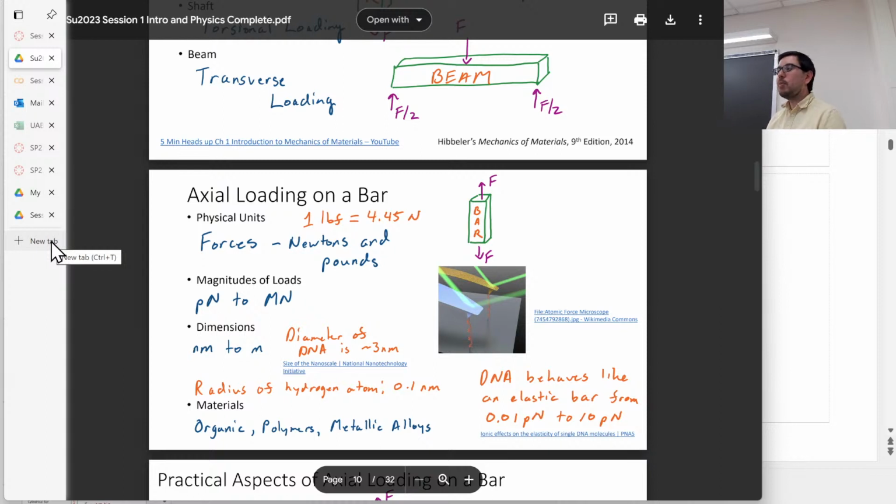Many of them are platinum base cured, and it will harden over time. Temperature accelerates it. One of the ones that we use in our lab a lot is called polydimethylsiloxane, PDMS, and the traditional material is made by Dow Corning, called Sylgard 184.